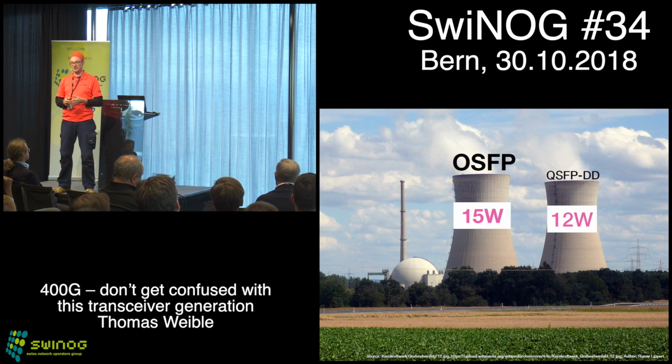Why is this power consumption so important? First of all, yes, we want to save power, but for the technology which you want to build into those transceivers, you have to drive the optical engines you need when you want to do PAM4 modulation. You need to drive a chip, an ASIC, which is able to do that. It needs power as well. So the more power you can get in there, the better. But for sure, you have to get rid of that power as well.